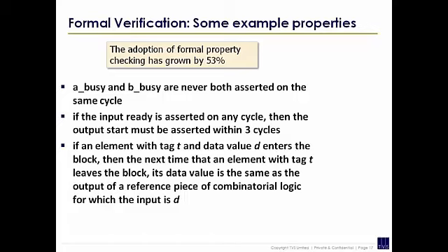And by the time you've got up to maybe 10 cycles, there's more potential states than there are stars in the universe. It gets too big too quickly. What our simulation does is this. What you're effectively doing in a simulation is finding one way through that state space. And if this already has more states than stars in the galaxy, the chances of you hitting bugs is quite low.